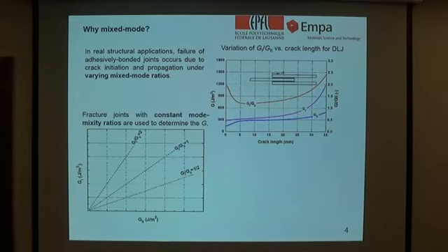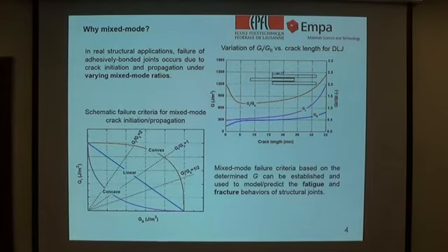So when we tackle this problem, we do some tests to find out the failure criteria for fixed mixed mode and also for pure mode 1 and pure mode 2. Then depending on the material characteristic, this can be a linear, convex or concave failure criterion.